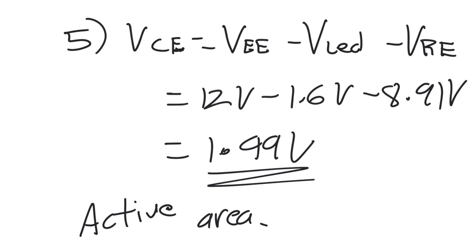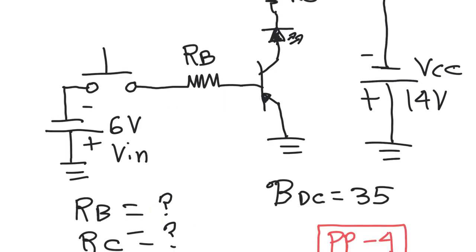As we're just turning on a light, there's no need to totally saturate the transistor. Why not have the high current gain? But there are applications, such as feeding into a controller or something, where you probably want to highly saturate the transistor. But again, as always, it depends on the application. This is our last problem.